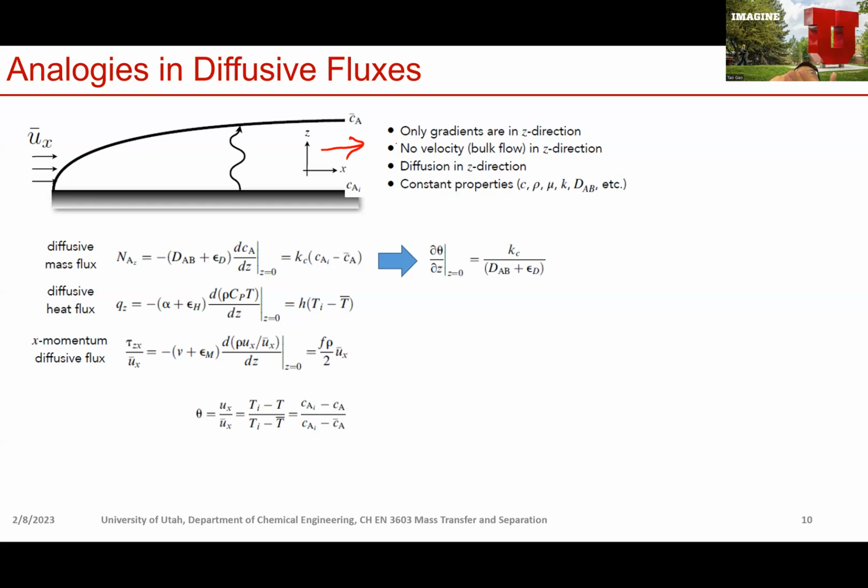However, if you have a turbulent flow, then you'll have eddies, and the velocity in the eddies will fluctuate. That will mix the species near the surface. That will create an additional mass transfer in the normal direction to the solid surface, and this mass transfer is much faster than molecular diffusion. Mathematically, it behaves similar to molecular diffusion. So that's why we can use a similar equation.